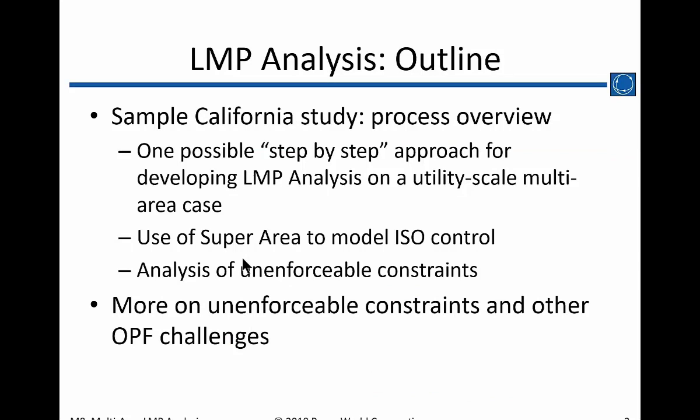This also uses a synthetic case, kind of like the examples that we did yesterday, but it's one that's on California. And the whole process of this topic goes through a step-by-step of one example, start to finish, doing things like limit monitoring setup, AGC setup, looking at generators, loading cost models, doing all that case development work prior to actually doing the OPF and then doing the OPF itself.